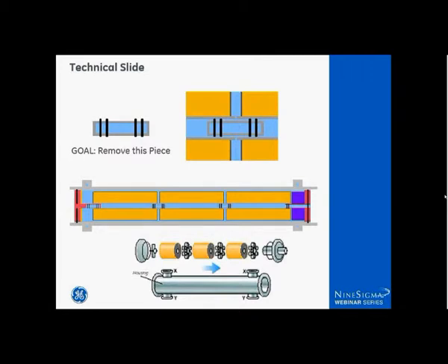In this picture, I've exploded diagrammed 3 elements to be installed in this particular housing. And in between each of those 3 elements is a connection that allows us to connect the central tube where the purified water is collected, and it will then be transferred to the very end cap as purified water. Water that is not purified actually exits the housings through the side pressure port depicted in the lowest picture.